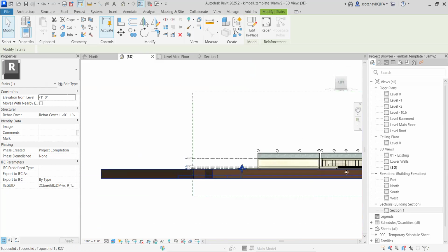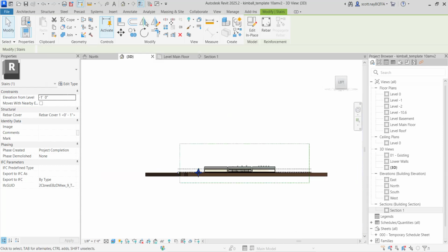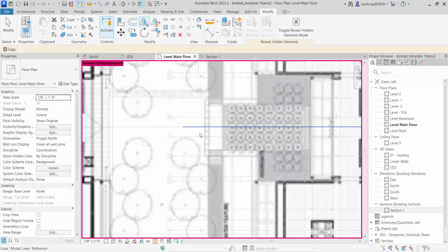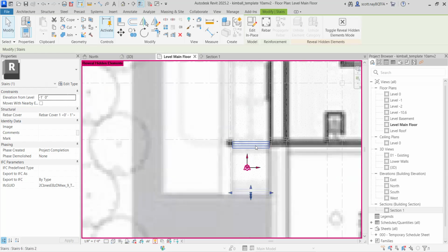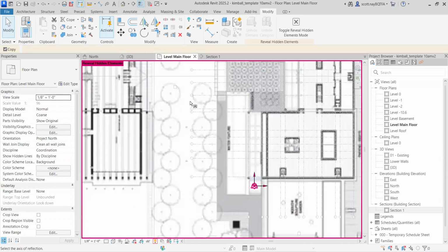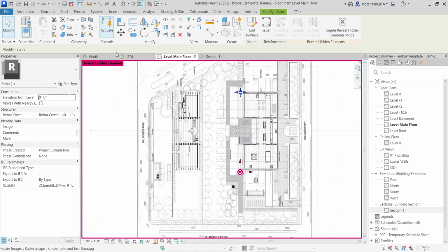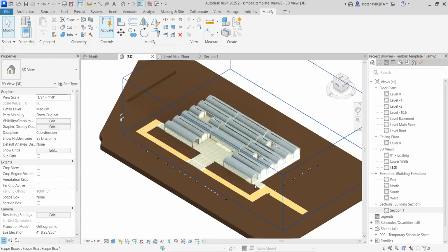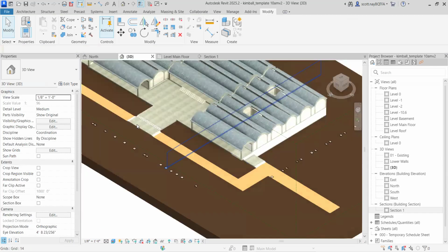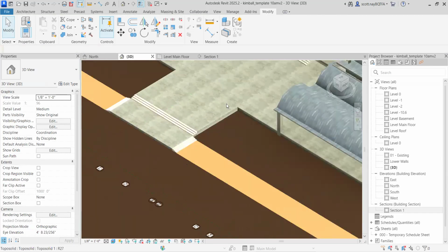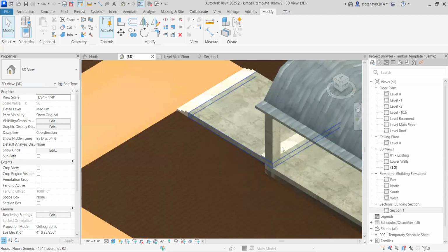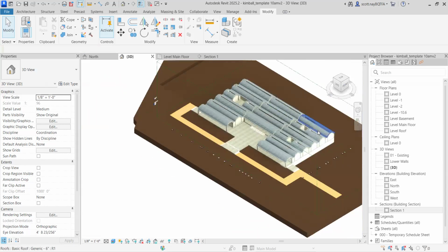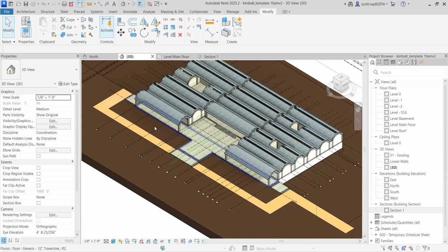So now I can mirror these and then mirror the other ones that are the correct height. But that's easiest to do from this view. So now I have my two lower ones, and I need my mid ones. Now it should actually look very good. I got 1, 2, 3, 4, 5, 6, 7, 8 sets of stairs that go from our main floor eventually down to the topography. All right, I'm gonna pause this one and start a fresh one for the water features.